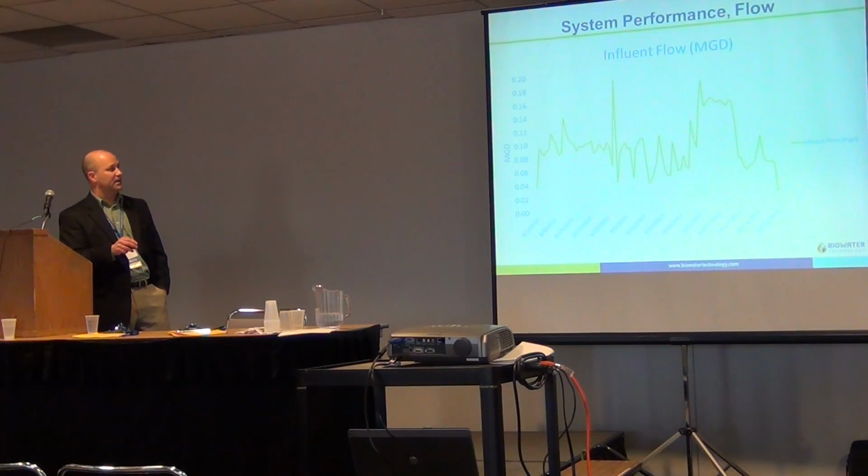So peak design flow, not only from a hydraulic standpoint but also from a treatment standpoint, was critical in this situation. And then it tapers off a little bit, the fruit processing is done, and then the school is back up and running, so the flow is back up. Near peak design was 140,000, and they pretty much sustained that in the first couple of weeks of school.